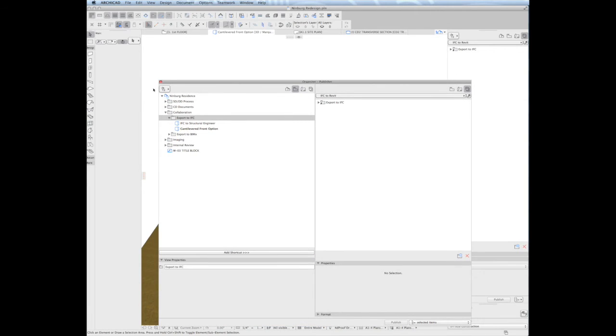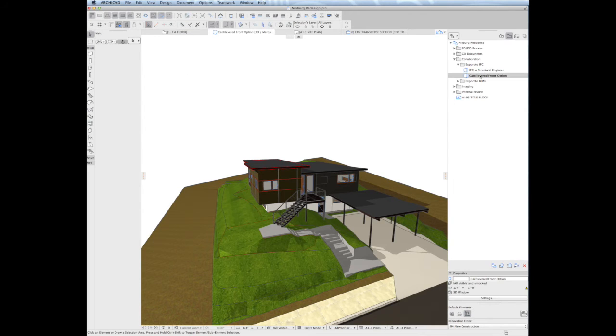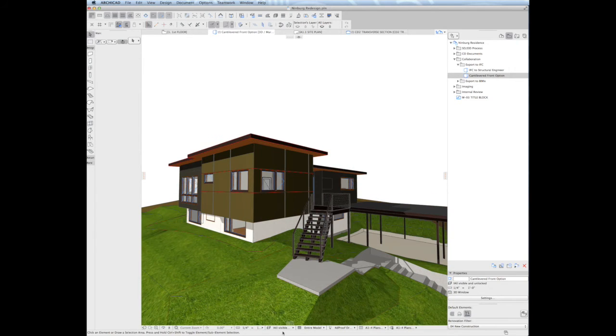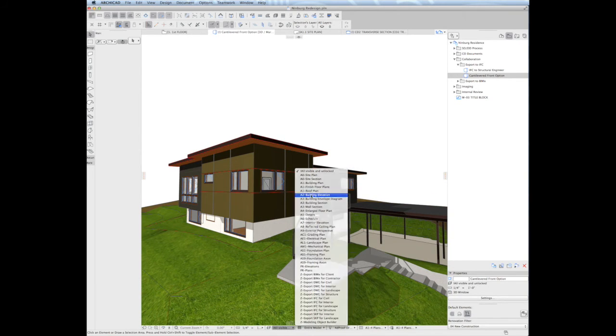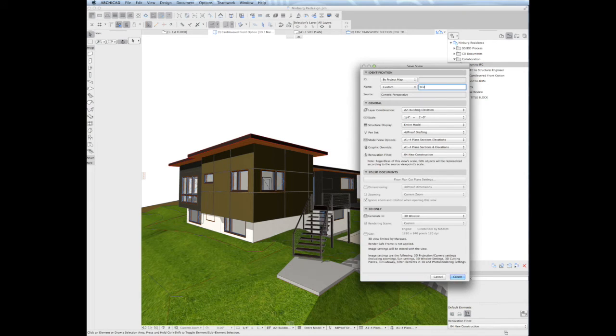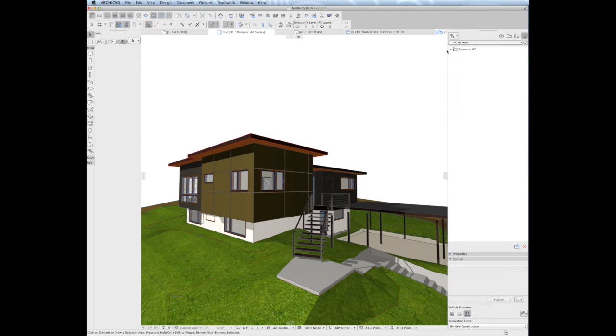That shortcut is actually really important, and I'll show you why. If I go back to my view map here, for example, and let's say I change the zoom, or let's say I adjust the layer combination and right click and save current view, and we'll call this just test as an example. So now I have another 3D view saved in here.